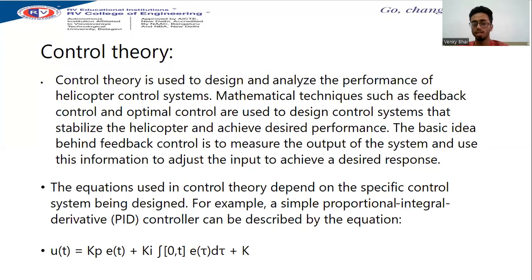The equations used in control theory depend on the specific control system being designed. For example, a simple proportional integral derivative controller can be described by the equation u(t) = kp e(t) + ki integral from 0 to t of e(τ) dτ + kd de(t)/dt.